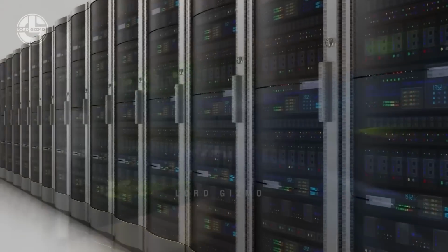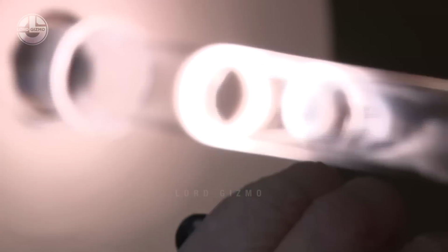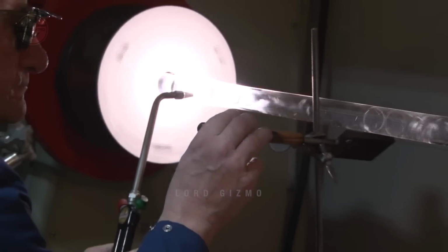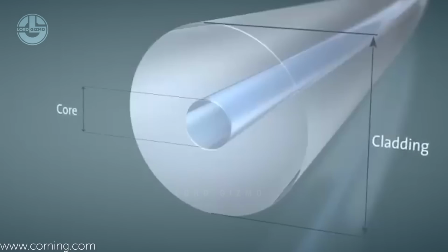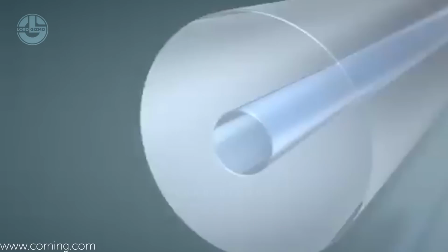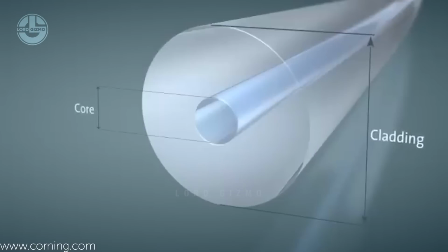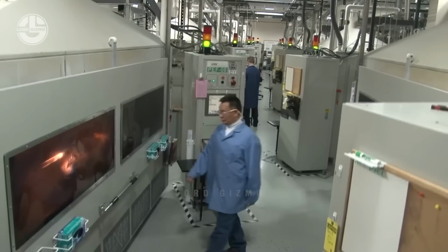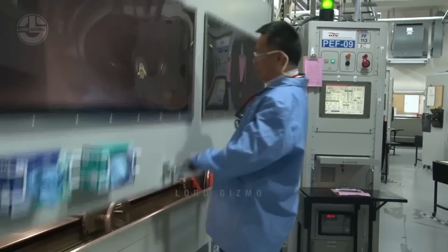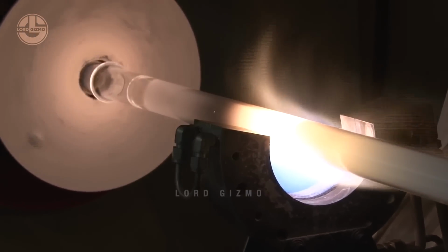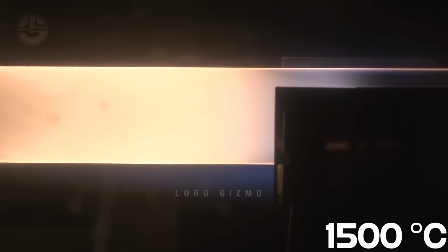Inventing something capable of changing the world is one thing, and starting its mass production is another. An optical fiber typically consists of a core, a glass tube in the center through which light transmits. The core is covered with cladding to protect it. The first step in manufacturing optical fiber is the creation of solid glass tubes. It is called a preform. This tube is rotated on its axis and heated to around 1500 degrees Celsius.